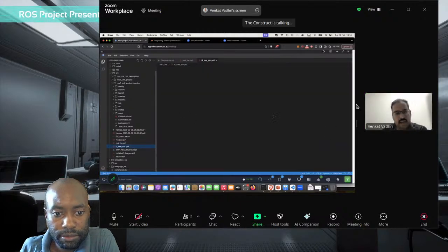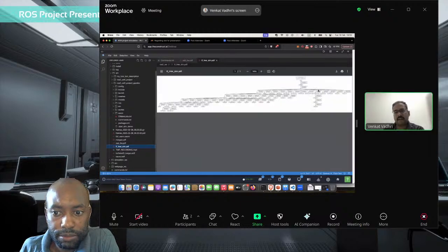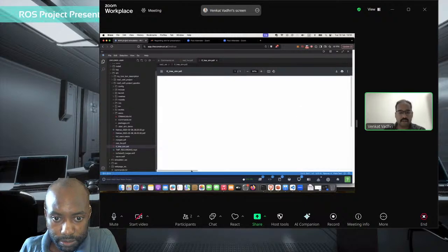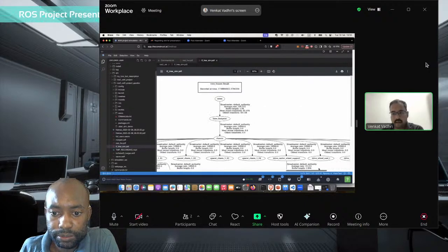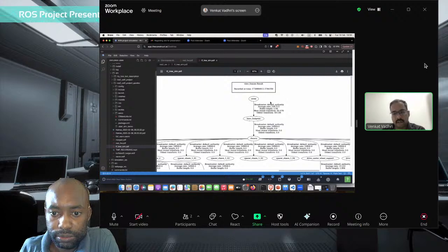This simulator inside the tree, actually, if I made a simulator inside the tree, it contains all the parts. It looks like this. Let me quickly zoom in to show you some relevant parts. There are a couple of different ways to construct this. I started with the base skeleton of the original robot so that the TF tree can be merged later, with odom and base footprint, and then I started combining the chassis.